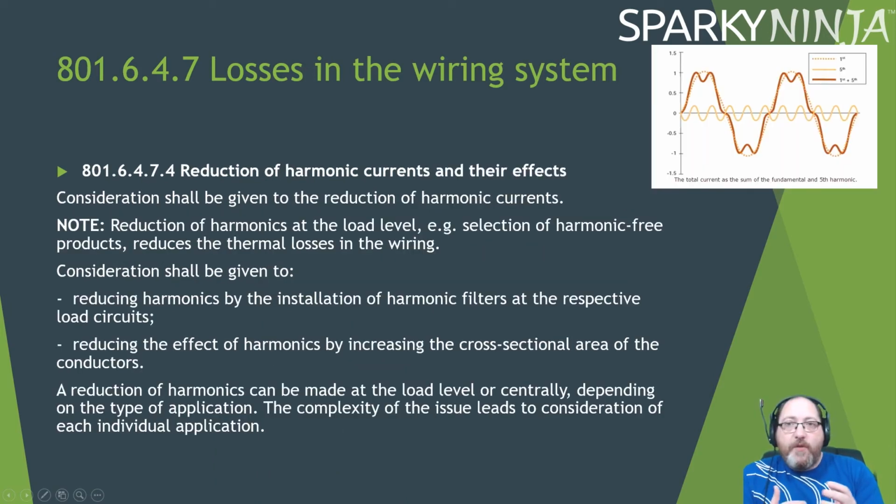Same as harmonics. Now, we've compensated for harmonics with more LED lighting and stuff. We've got to make sure that the equipment is either harmonic free or it has power factor correction, which will help with the harmonics. But we've got to consider reducing our harmonic content as best we can. Harmonic filters or whatever.